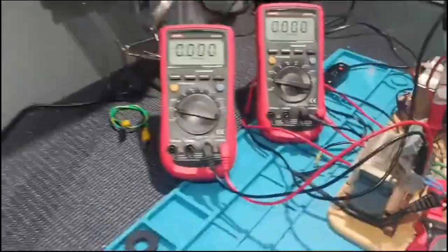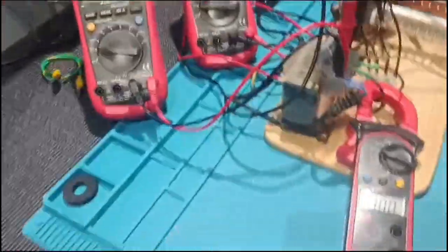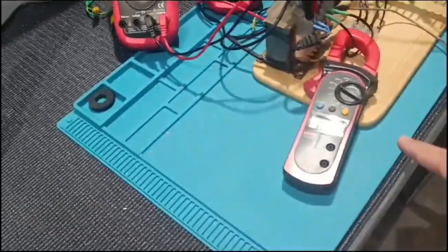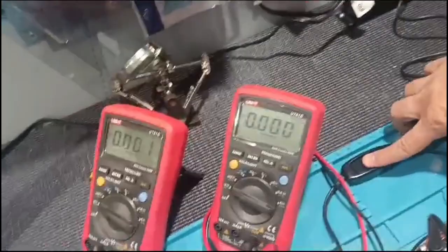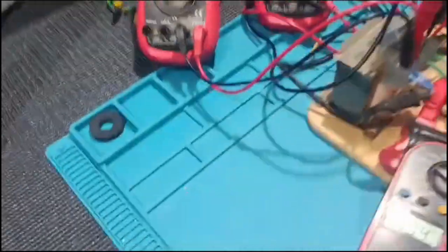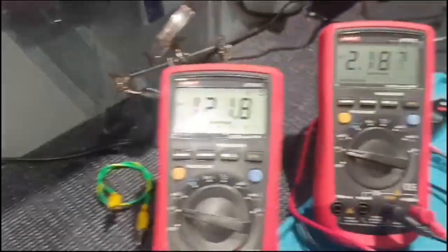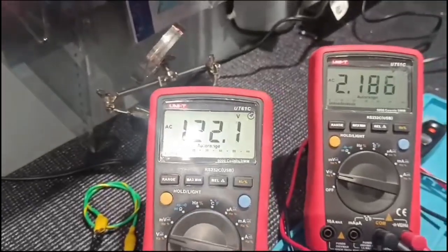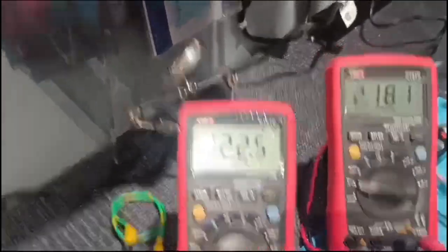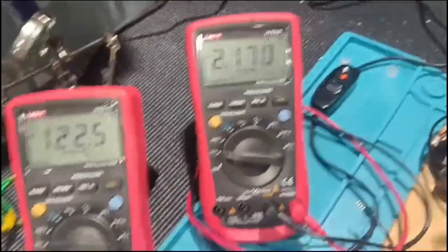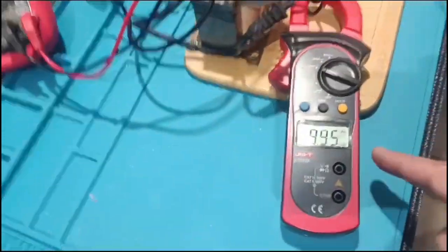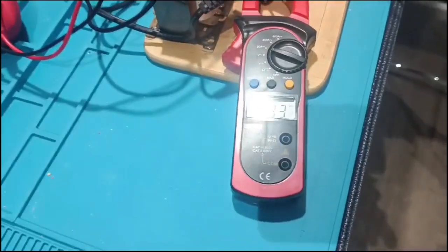So, we are ready to fire up. I'm expecting double the current, like before, like shown in the PowerPoint presentation. So let's fire up. What we can see here is always 120 to 121.8 volts at the input. This time the voltage in the output is even lower, and that happens because the current has been doubled in a parallel configuration.